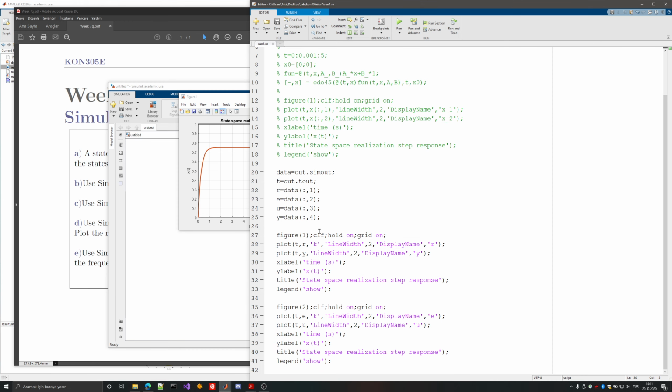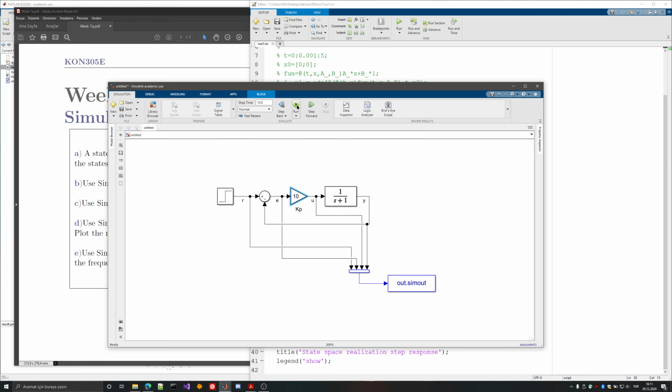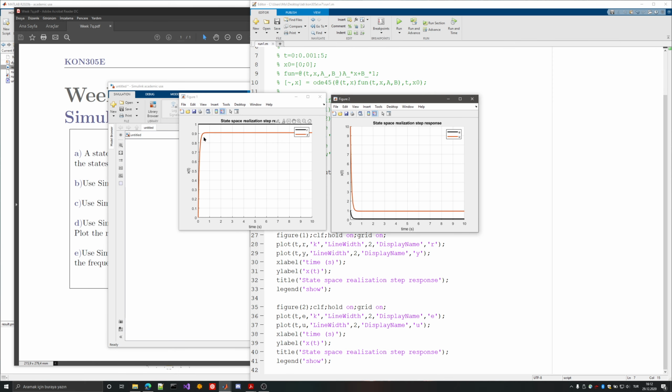So it will approach the one line. So I will have approximately, not exactly, but approximately 10% steady state error. Approximately, because 10 divided by 11 is the actual error band here. So I can see that higher and higher control signal will give a better, let's say, response.